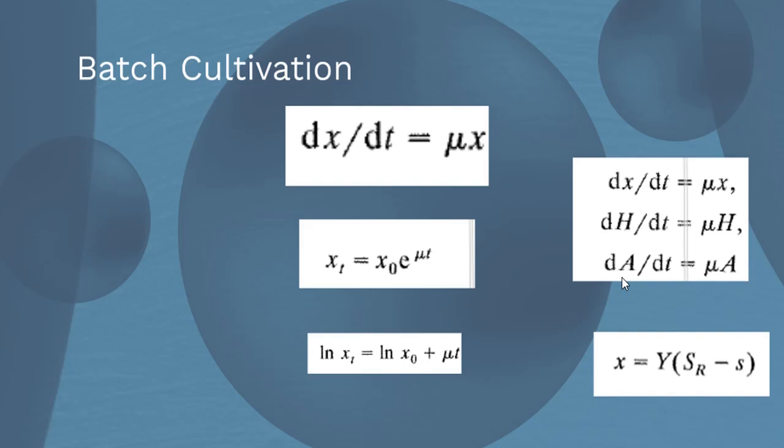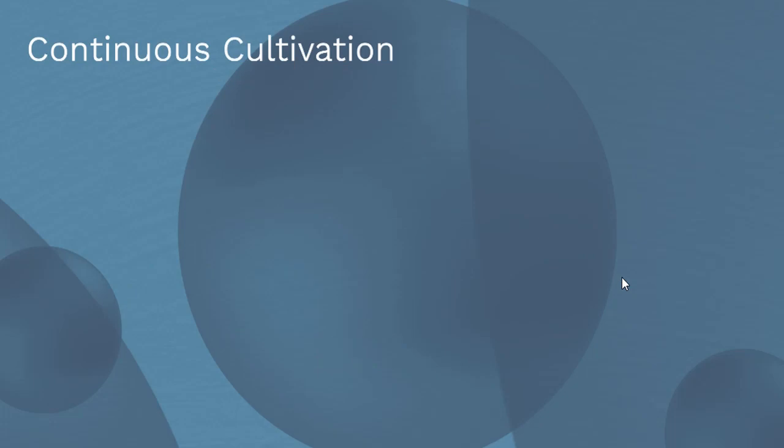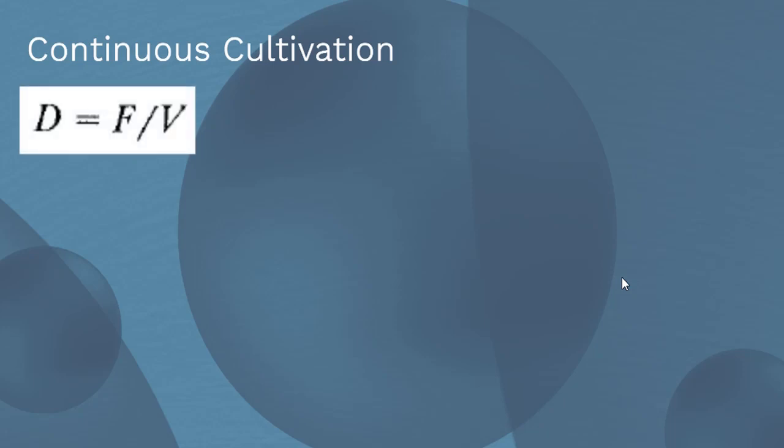be continuously estimated in order to determine the viable cells present in the system, and the specific growth rate of the cells and product formation kinetics has to be ascertained. In a continuous stirred tank reactor, changes in the morphology of the culture can be studied. The dynamics associated with the changes in the culture composition are of great importance to any bioprocess industry, where dilution rate is the significant parameter that affects the efficiency of a bioprocess and is given by the ratio of feed flow rate to the volume of the vessel.